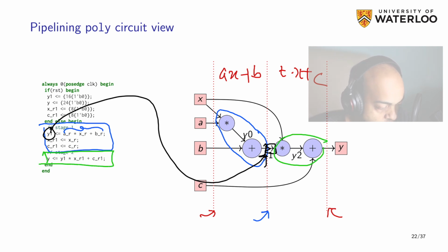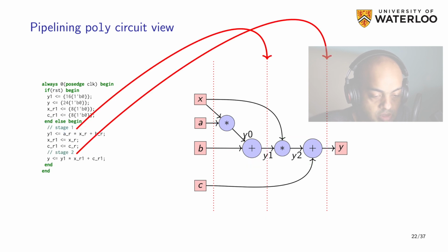So you are doing these 2 sets of multiplies and adds. And then the output Y is going to be this chunk of registers here. Okay. So now you only have 2 stages. So less Verilog code to write. More work in an individual stage, so we are going to sacrifice some performance, and what we get is these 2 blocks of code correspond to these 2 stages of pipelining.